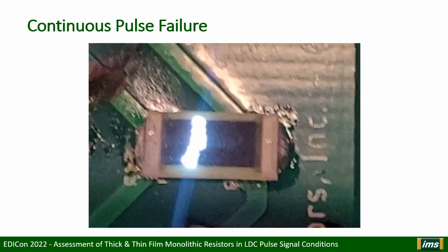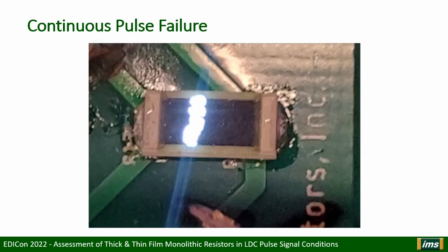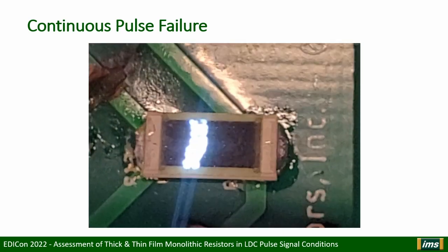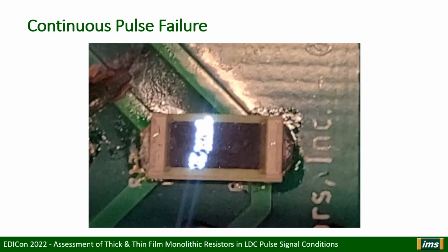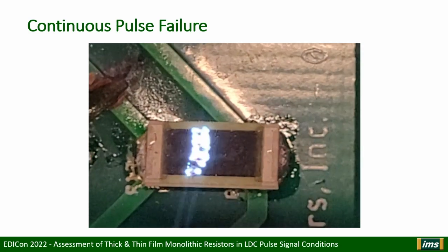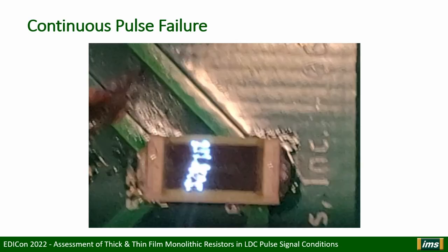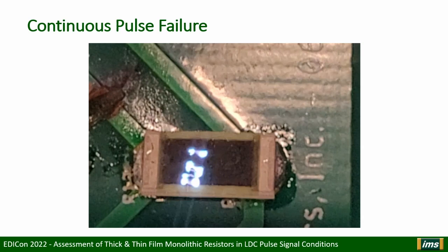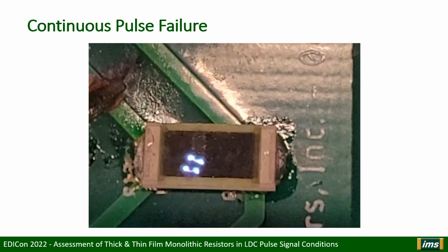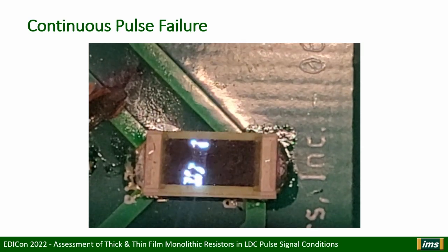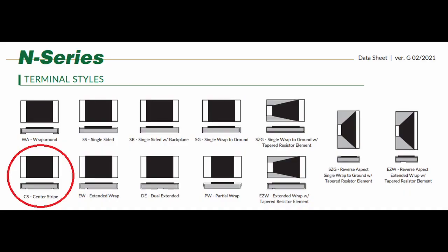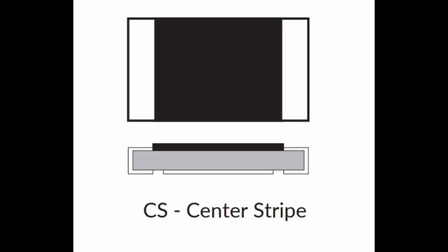Even though, for example, aluminum nitride has a thermal conductivity rating of 170 to 210 watts per meter Kelvin, it's the film that can pay the price, and the film really doesn't care about average power. On the other hand, if a stable setting can be reached for the film, using a component made from a more thermally conductive substrate can contribute to reducing risk, especially if the heat generated doesn't only pour back into the traces. Terminal configurations exist that are different from the standard wrapped SMT part and can offer excellent thermal sinking benefits